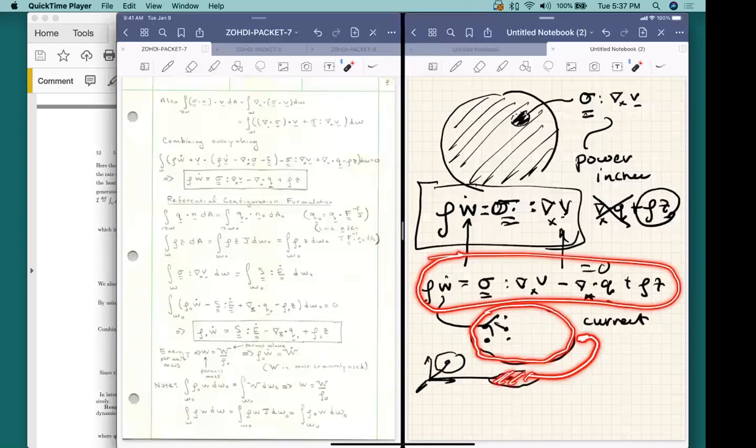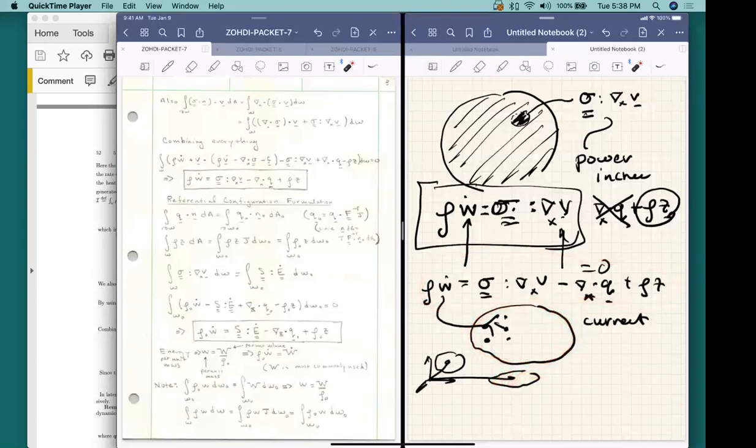So this is a snapshot of the object, and at every point inside the body, this is the equation that holds. So what we're going to see later in the semester is we're going to use this equation over and over again, because we're going to basically take a laser, for example, shown here, and we're going to zap this thing and hit certain points in the body and heat them up. Well, the way we account for the laser is exactly from this term and this term, from heat conduction and heat input. This is a pretty flexible equation because it allows us then to start to characterize for different manufacturing processes, different types of Q, different types of input, different types of stress, different types of material storage.